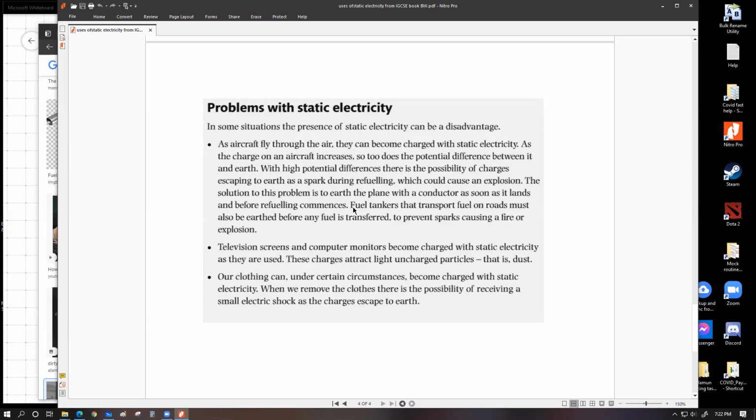that might lead to an explosion. Here, every statement has "may" or "might" or "could" written, because there is no guarantee that a spark will happen, and no guarantee that a spark will lead to ignition, and no guarantee that ignition will lead to explosion. It is possible for some rare cases where all of these three things become yes, and we can actually have a big catastrophe, which we don't want to happen, but these are all bound by probabilities, not certainty.